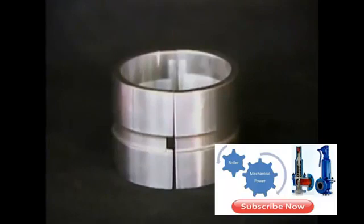Radial bearings support the compressor shaft. The bearings are lubricated to allow the shaft to rotate freely inside the casing. But the bearings prevent most radial movement, which is movement that's perpendicular to the shaft. Another device that's important for the proper operation of a compressor is a gas cooler. Coolers are used to remove heat that's produced when gases are compressed.